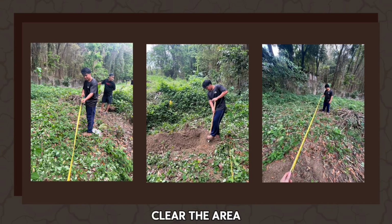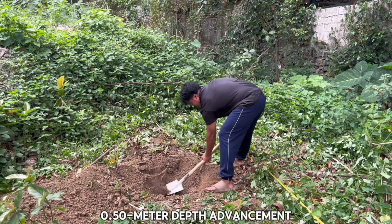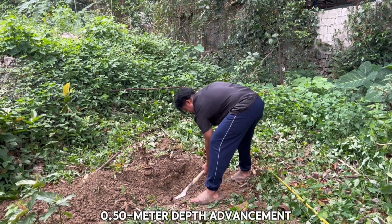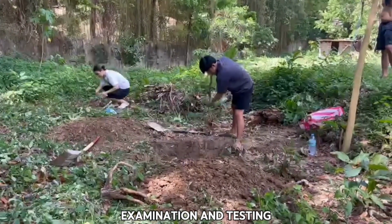Next, clear the area of grass and vegetation where the soil samples will be collected. Establish an alignment of 3 boreholes, spaced approximately 3 meters apart, using appropriate digging equipment. Bore the soil until the required depth is reached. For every 0.5 meter depth advancement, collect a soil sample for examination and testing.